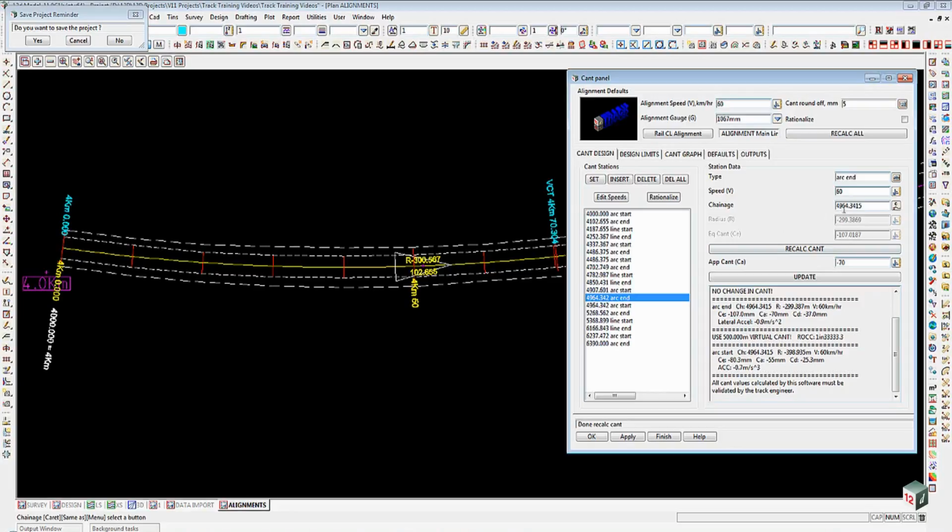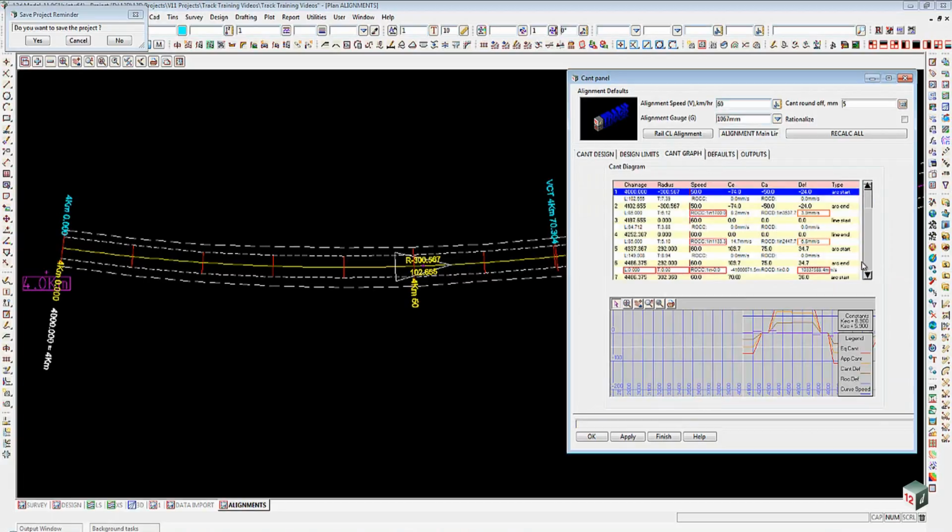I'm going to come across to the right hand side over here. I'm going to change that down from 64 down to 54. I'll update that one. Then I'll come down to the next line down here. I'll update that from 64 to a 74 and update that. That basically has told me that I've now got a 20 meter distance through those portions in there. Now, does that fix it? Not necessarily. I'd still have to probably go through and tweak it a bit more, but we can now see that we are achieving a length of 20 meters in there.